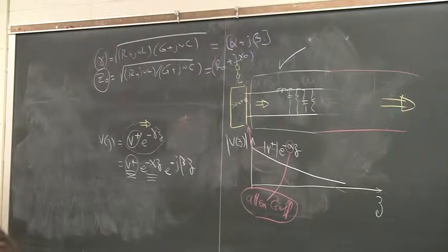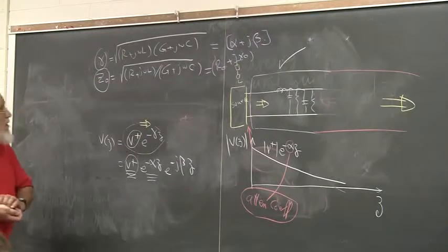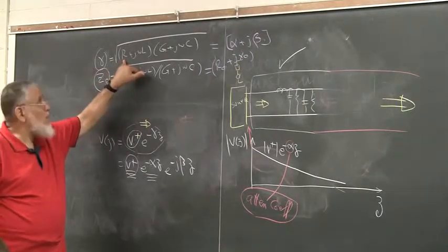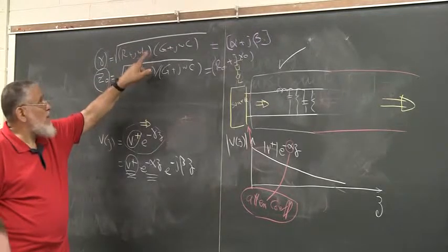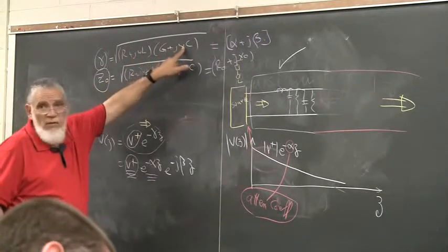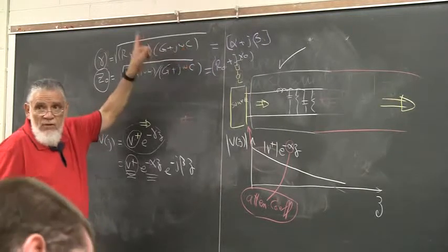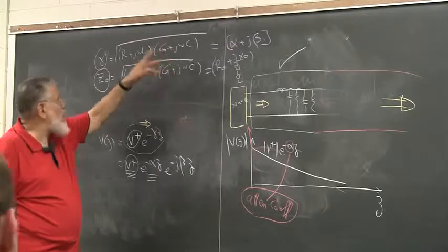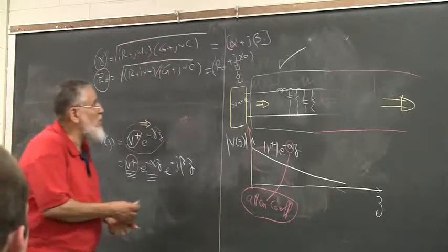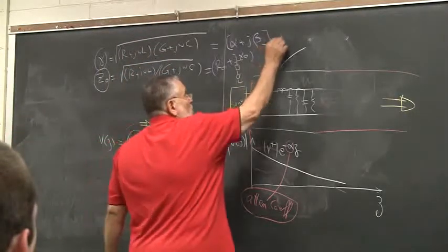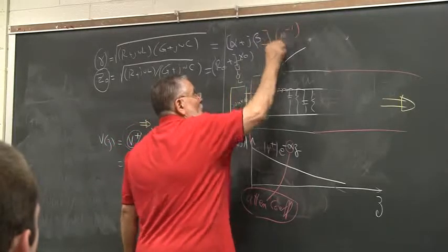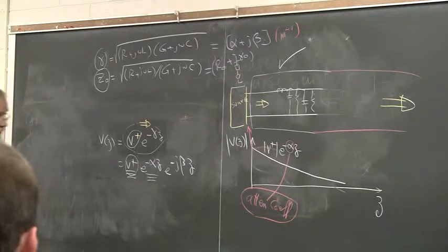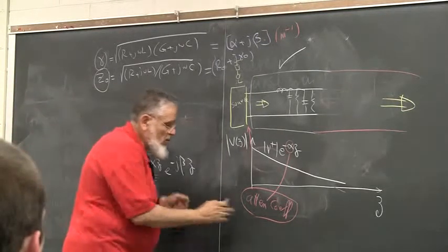Now, what are the units of alpha? If I go back here, that was ohms per meter, Siemens per meter. Ohms and Siemens cancel each other, and we have per meter per meter, and the square root is per meter. So the units here are meter to the minus 1. That's all what's left from my units. So alpha's units are again meter to the minus 1.